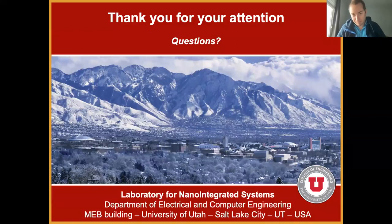But now here's the problem. Evaluating a logic synthesis framework with an FPGA is always a complex beast. Why? Because FPGAs have this notion of black boxes. You have these hardwired adders, for example, that very often are handled at the behavioral synthesis level. You look for your y equals a plus b and say, oh, that's an adder, let me map that to it, and you basically bypass your logic synthesis step to do that. So that makes things harder to evaluate.